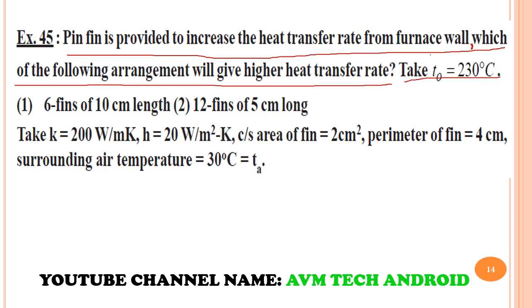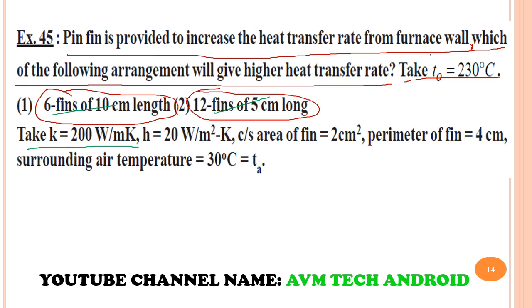T0, that is base temperature, 230. The first case is 6 fins of 10 centimeter length, and the second is 12 fins of 5 centimeter length. So we are having two cases, case number 1 and case number 2. Thermal conductivity is given 200 watt per meter Kelvin. H, that is the convection heat transfer coefficient, is given 20. Cross section area of the fin is 2 cm squared. Perimeter is 4 cm. Surrounding temperature is 30 degrees Celsius.